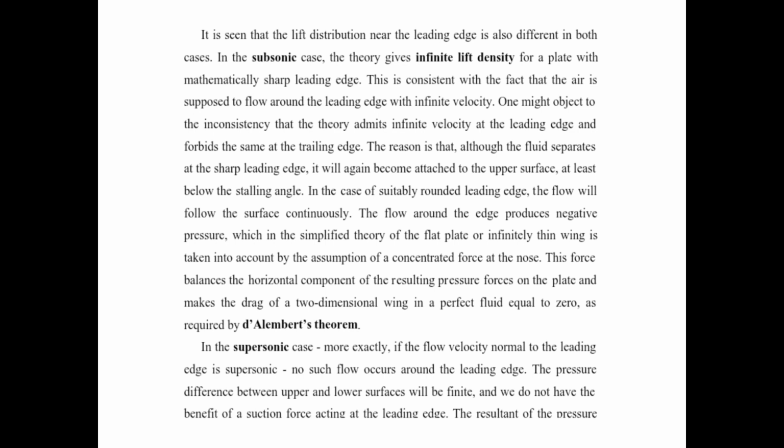In the case of a suitably rounded leading edge, the flow will follow the surface continuously. The flow around the edge produces negative pressure, which in the simplified theory of the flat plate or infinitely thin wing is taken into account by the assumption of a concentrated force at the nose.